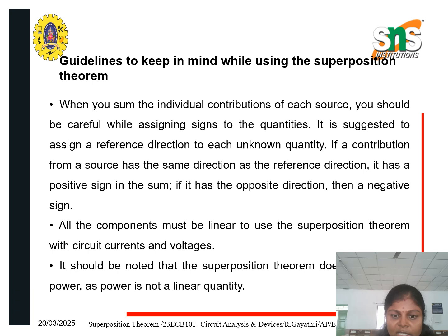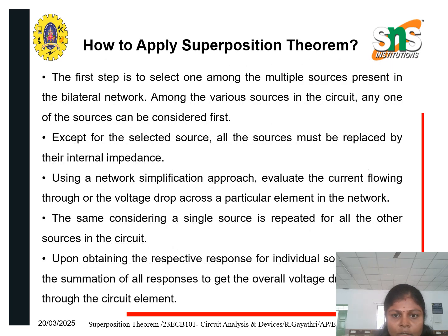All the components must be linear to use the superposition theorem with circuit currents and voltages. It should be noted that the superposition theorem does not apply to power calculation, as power is not a linear quantity. How to apply the superposition theorem?